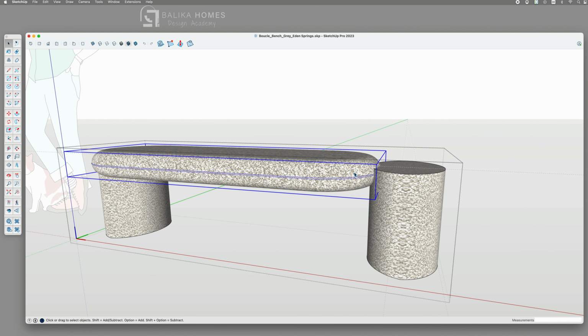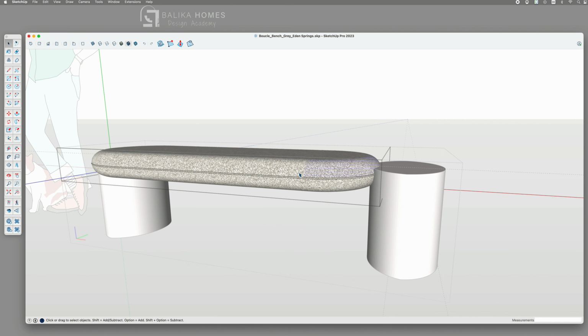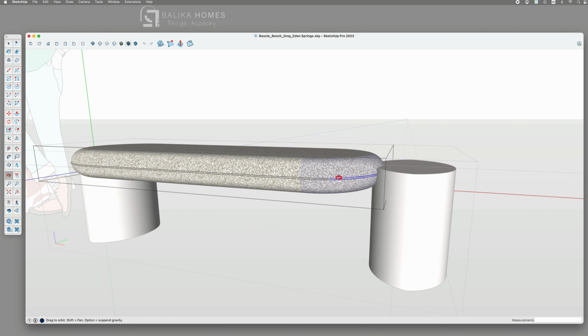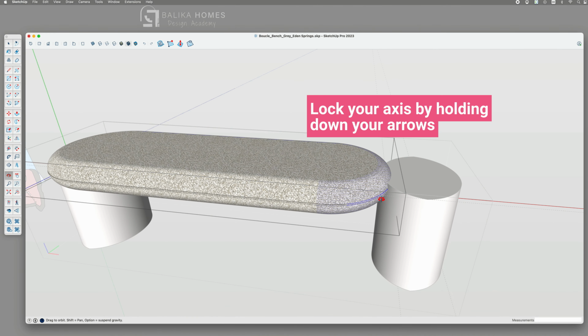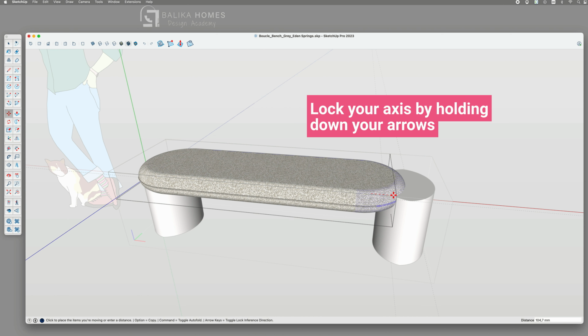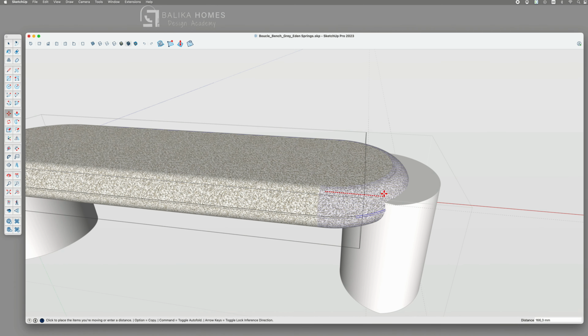Then you can even go deeper inside one of the single groups, like the middle part here, until you can select the surfaces and edges. Ensure precise selection by choosing the correct sections of the surfaces and edges while excluding the upper surfaces. In some instances, moving the lines along the edges can automatically move the surfaces with them. If materials are already applied to the surface, they will remain in place, and SketchUp will seamlessly continue within the existing texture.